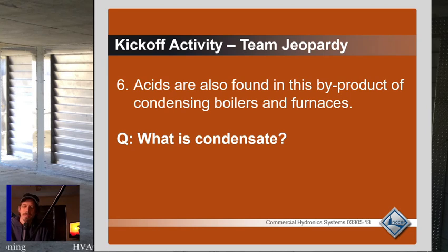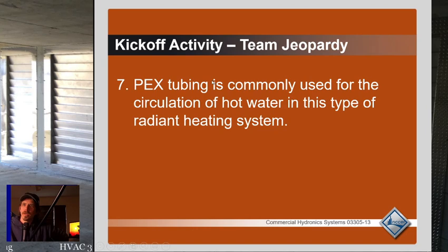And the city's mainly trying to protect themselves on their main piping. They don't care if you eat up all the piping in your building. They don't want you to eat up their older mains and stuff like that. So that's why we do neutralizers on flue condensate.